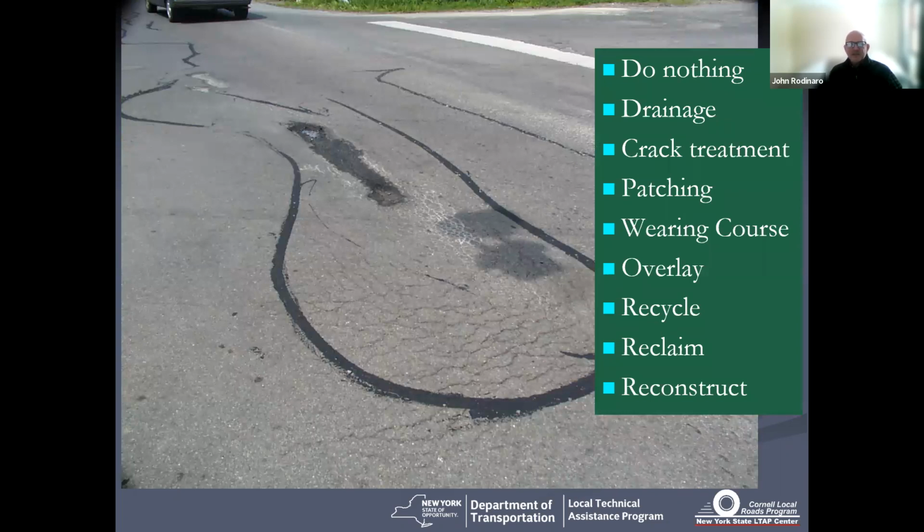The one thing we've got to consider is to look at those holes a little bit more. You've got standing water in those holes, and it's not evident that there was any recent rainstorm. So that water's coming from someplace, and you've got to figure out where that water's coming from. So you've got to do, like you said, some coring or a test pit. You've got to do some further investigation before you do any kind of pavement repair.